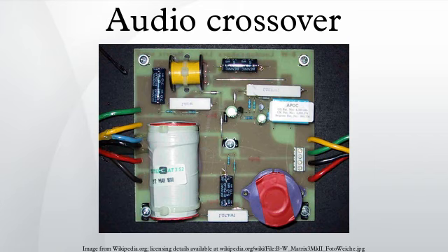The power amplifiers are directly connected to the speaker drivers, thereby maximizing amplifier damping control of the speaker voice coil, reducing consequences of dynamic changes in driver electrical characteristics, all of which are likely to improve the transient response of the system. Reduction in power amplifier output requirement. With no energy being lost in passive components, amplifier requirements are reduced considerably, reducing costs, and potentially increasing quality.